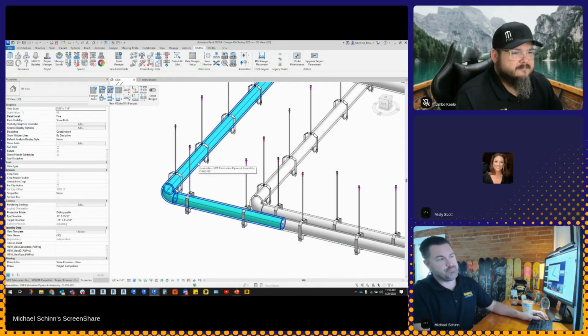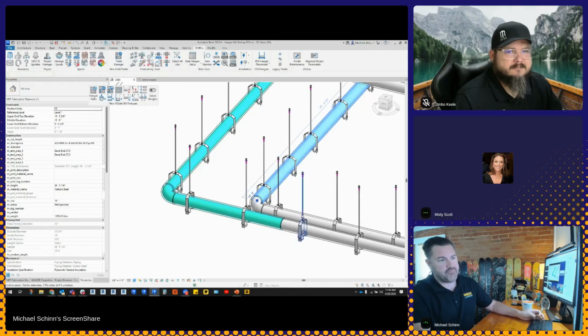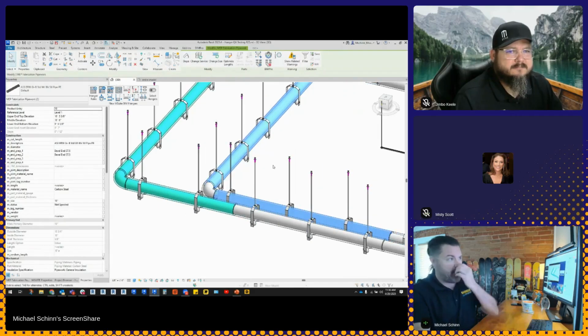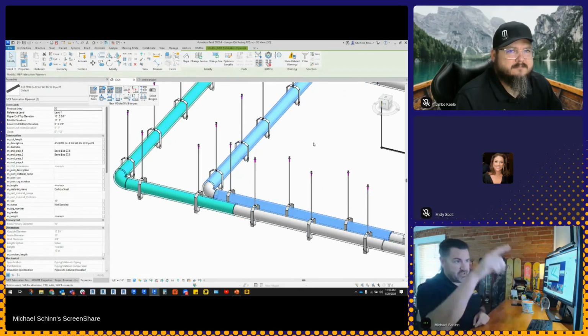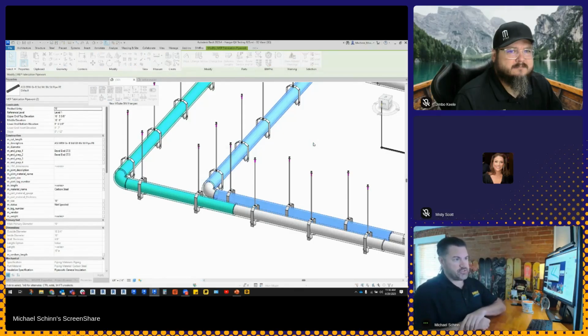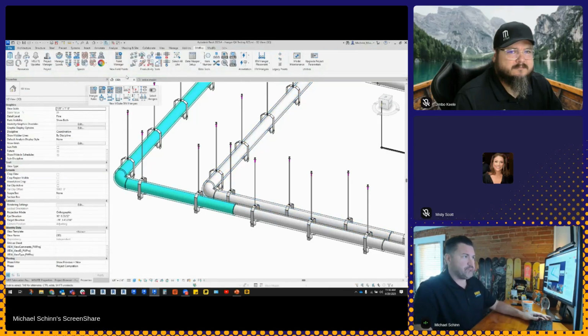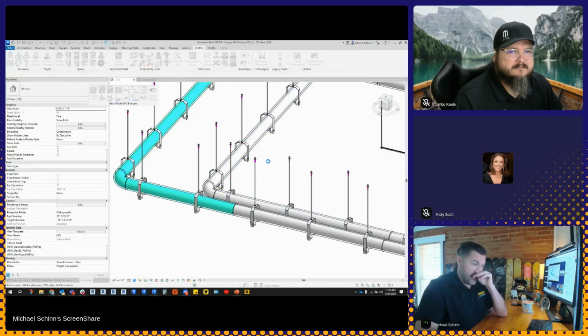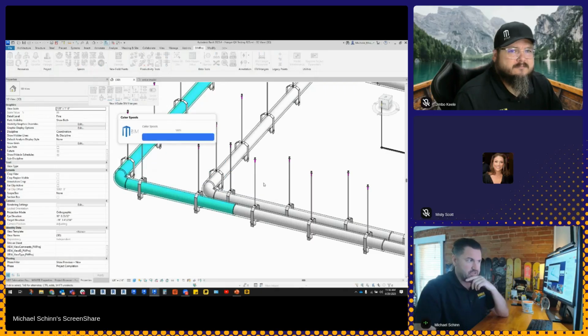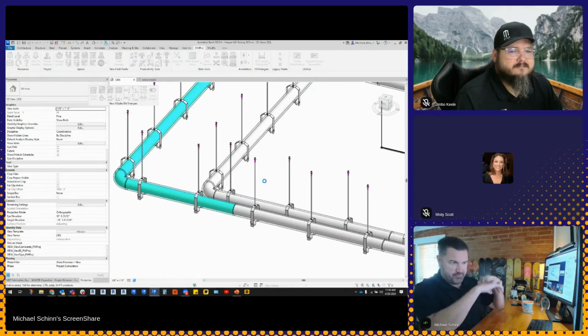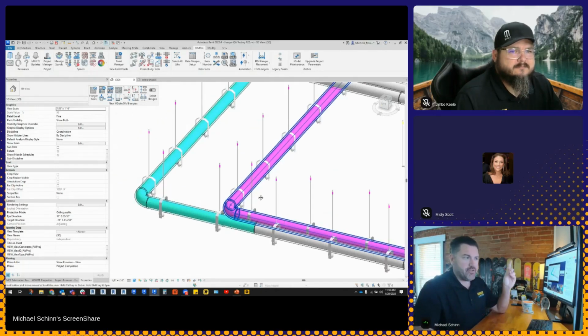Yeah, I just made a simple spool. Our tool allows you to grab onto stuff. When I say I want that to be a spool, I'm not going to grab the hangers, but I'm going to say I want that run to be chilled water supply number 2. It's going to grab anything between those two. I didn't add them because we're using Revit assemblies to do our spooling, but yes, you can add those to a spool and do all your special schedules with that. Look at it from this different standpoint.